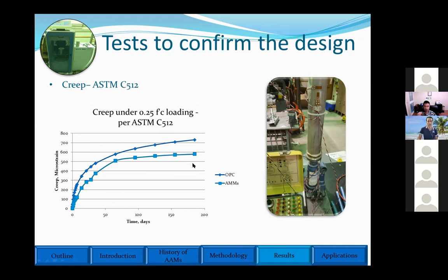But for the creep test, it's good to know that the creep after 3 months, for example, imagine this, we wait 3 months for our concrete elements. The creep problem is that over time, we have excessive deflections. For example, we are pouring a concrete beam on top of the elevators, and then over 3 months, we cannot open and close the door of the elevator. It means that we need to calculate for the excessive deflections of our concrete elements over time.